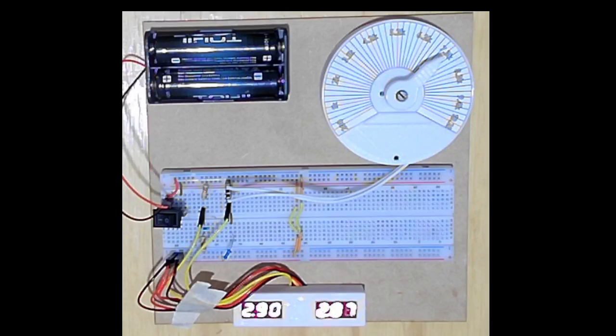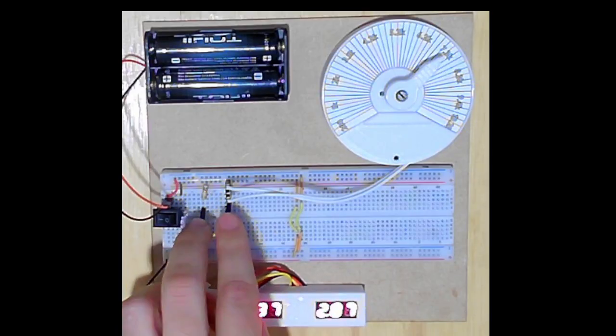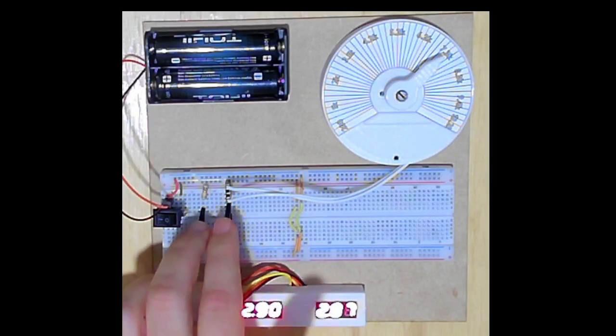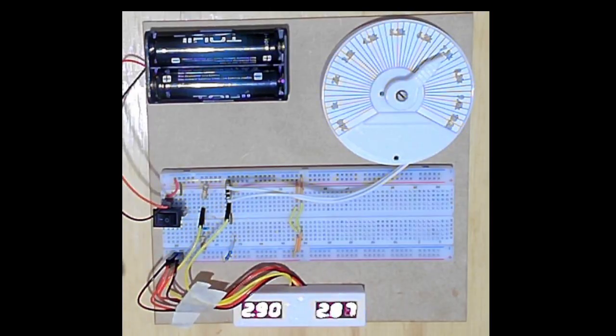So this is my explanation. Hope it's useful for you. And in your case, you will not have two voltmeters, but if you measure between these two, you are searching to get 0 volts here, right? When you get 0 volts, the relation between the first two resistors and the resistor 3 and the unknown is the same relation, right? So you can design for whatever values in the principal branch and in the second branch, right? So try not to use the same values as me. Use different values, so it will be more interesting for you to try that.